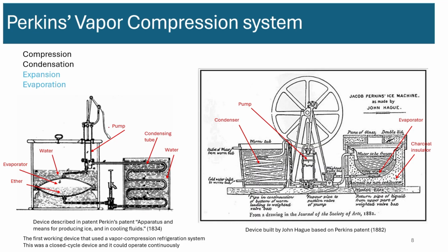It had a pump, which will draw the vacuum of ether. So you can see a chamber full of ether. Okay, so you pull a vacuum here, ether vaporizes. When ether vaporizes or evaporates, it creates a cooling effect, and that cooling effect cools the water around it, creating the ice that they were looking for.